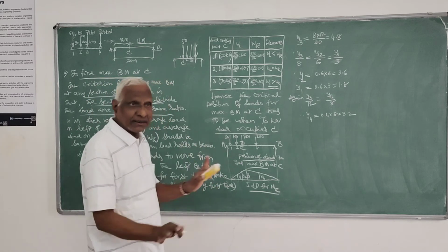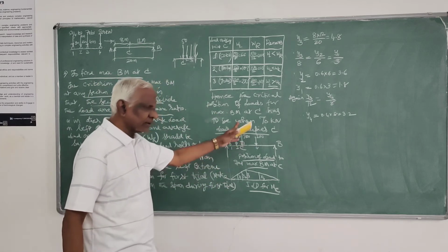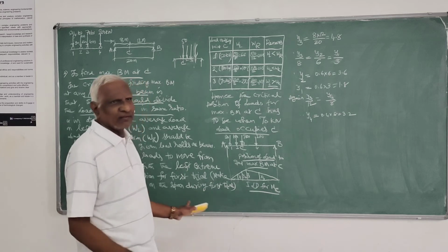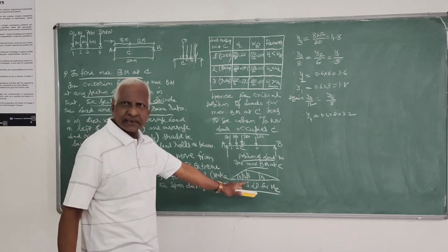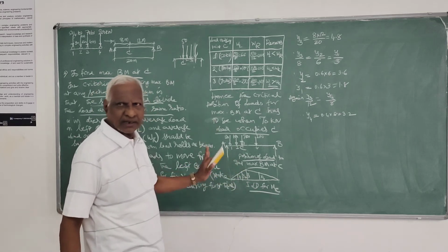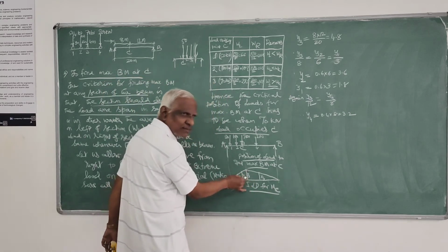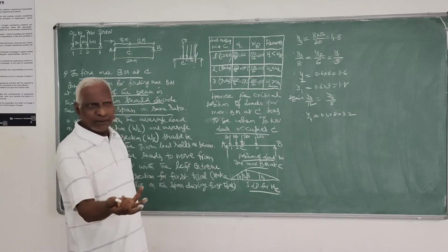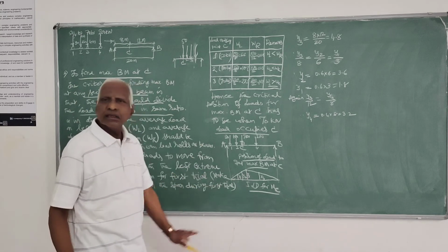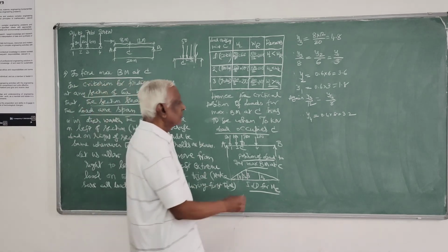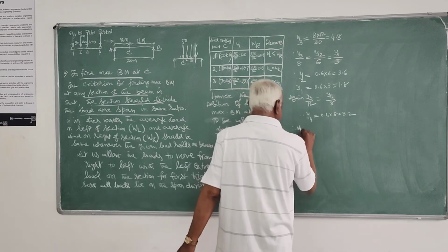I have given the complete procedure now, how to compute the ordinates by similar triangles, everything. So don't make any mistake in this. Only by similar triangles you have to get the ordinates. After getting one of the ordinates, that's the maximum ordinate, that is known, ab by L, from that standard influence line diagram. So therefore, MC is equal